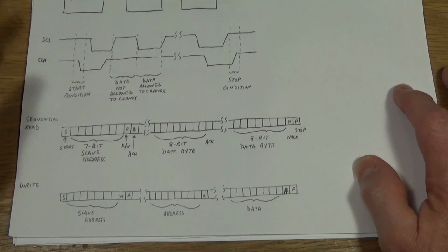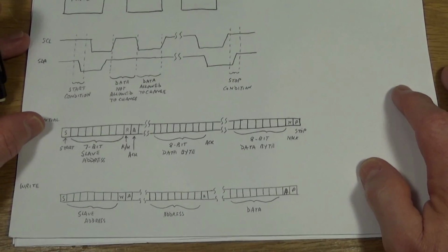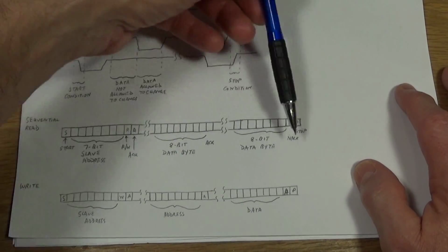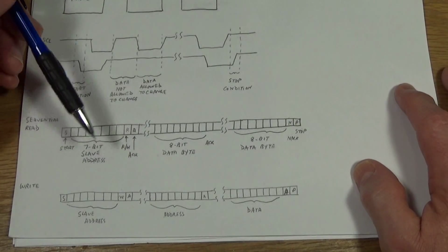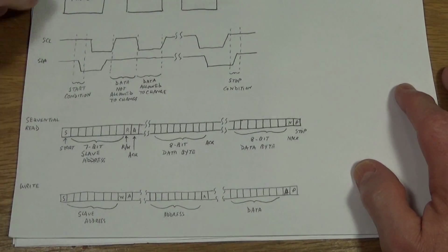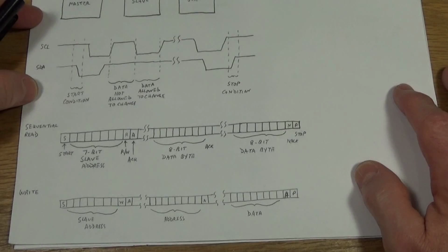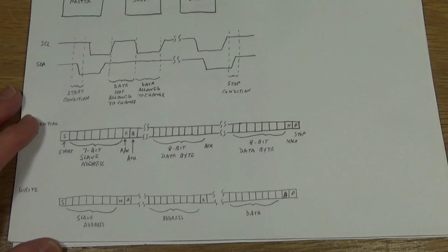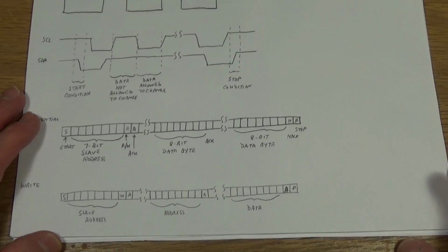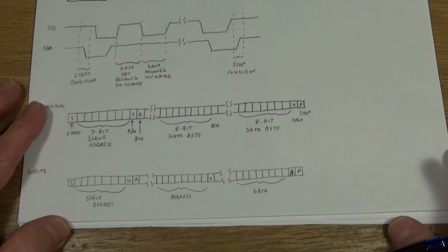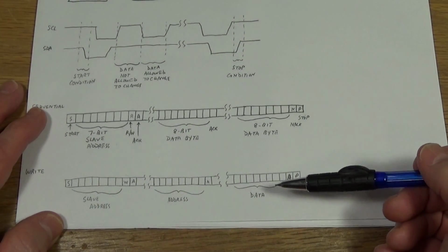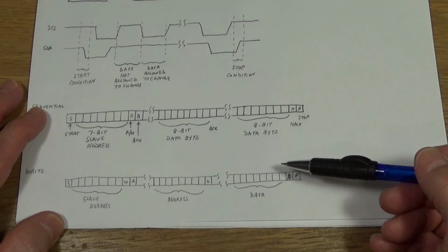it's finished. Now typically when you're communicating on the bus, you're not going to do this kind of a communication because you don't know where that address pointer actually is. Once it's set, it stays there. It doesn't get lost unless the power is turned off or something like that. But now what I'll show you here is a write to the bus, and I'm going to write a single byte of data to a single register in the device.